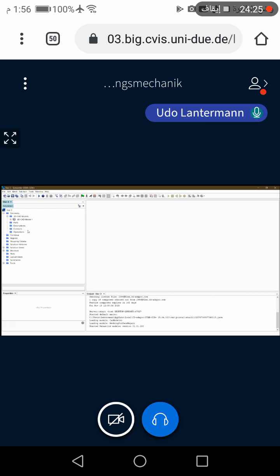And the next step is we have to create a part from this 3D cut model. That means we click with the right mouse button on this 3D cut model 1, which we have created just now. And from the options, choose the option number 4, new geometry part.